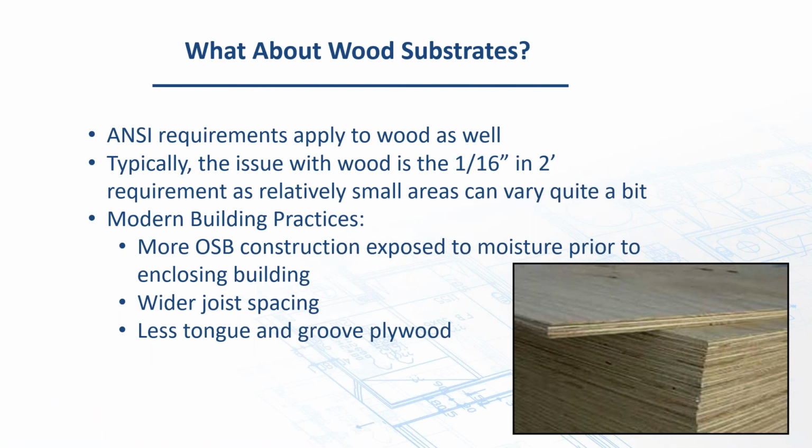What about wood substrates? What if you're going to go over plywood? Residential as an example. The same substrate tolerances prevail. If it's greater than 15 inches on one edge of the tile, you need to be a 1/4 inch in 10 feet. I'm sorry, I apologize. Greater than 15 inches, it should be an 1/8 of an inch in 10 feet, 16th of an inch in 2. That can be tough when it comes to plywood because you've got a lot of exposed edges. So you've got to check all those edges, make sure it's not delaminating or substantially weathered.